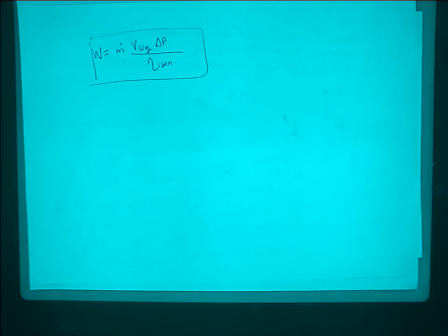When you expand, when you do the opposite, you decrease the temperature. So actually, that's a first indication that your result should be lower than the inlet. Always decrease for an expander, yes. Compressor is always increase.